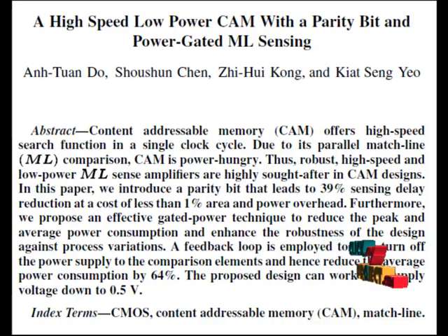Next, the search line driver broadcasts the search word onto the differential search lines, and each CAM core cell compares its stored bit against the bit on its corresponding search lines. Match lines on which all bits match remain in the pre-charged high state. Match lines that have at least one bit that misses discharge to ground. The MLSA then detects whether its match line has a match or miss condition. Finally, the encoder maps the match line of the matching location to its encoded address.